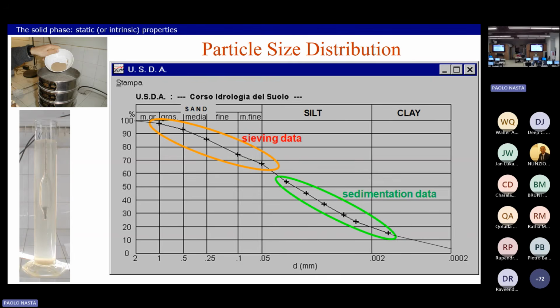So there are many equations available in the literature, and we can choose different equations according to the number of points. Of course, equations that are based on a few parameters are probably better in this case when fitting 11 points, but there are also multi-parametric equations like the Fredlund, for instance, that can be very efficient at the cost of using a high number of parameters.